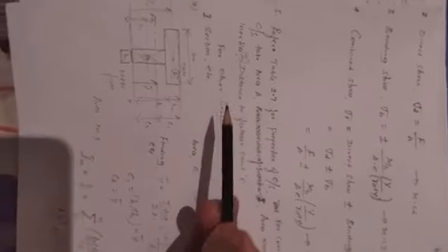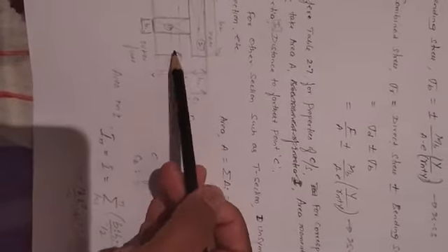For other sections, some are not in the table, such as the T section and unsymmetric I section. Then remember this formula for other sections such as the T section and unsymmetric I sections. For the T section, see this geometry. Now this is the inner fiber. Always the inner fiber has more thickness, the outer fiber less. For the T section, what will be the area? As you know, here portion 1 and portion 2. Area is the sum of all the areas of the portions, A1 plus A2. A for a rectangle is B into H. Finding CG, how do you find the CG? Here from the outer fiber you consider Y bar.